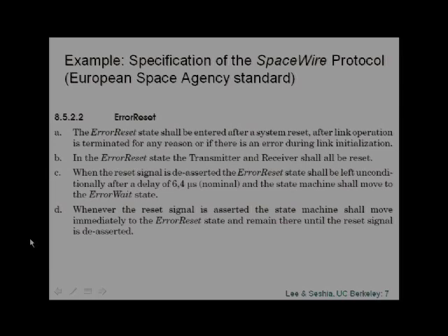Think of SpaceWire as essentially a standard like TCP/IP, right? It describes how communication occurs on board the spacecraft between different computers, different sensor actuator arrays, and through routers. So you effectively have a network on board a spacecraft where different subsystems are connected through routers.